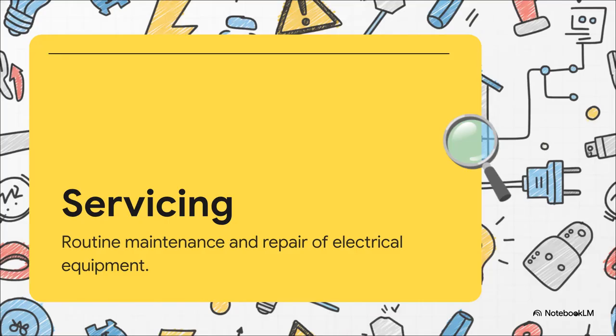Next, we really need to clearly differentiate servicing from reconditioning. Servicing is just your basic upkeep, routine maintenance, or swapping out a worn part with an identical replacement to ensure operational performance. Reconditioning, on the other hand, is a major overhaul. That requires a much stricter set of evaluations, approvals, and often recertifications.